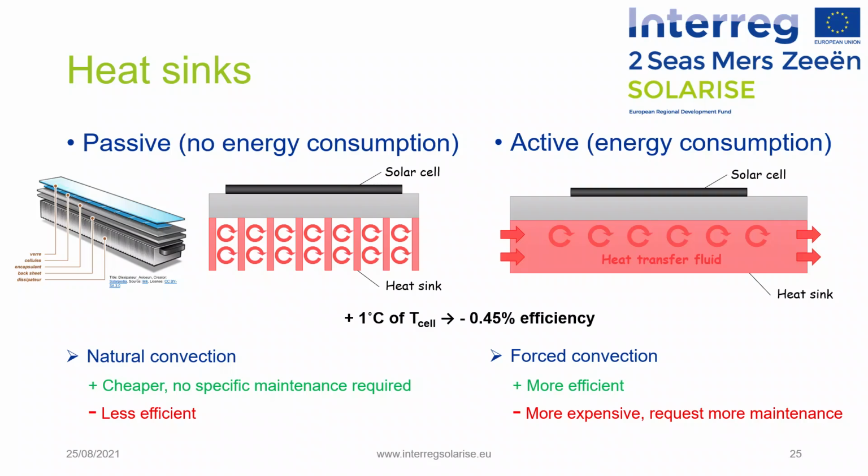Passive thermal dissipation cooling systems are mostly thermal radiators inspired by the forms that already exist in the field of microelectronics for cooling microprocessors engraved on silicon wafers. They are less efficient than active cooling systems but are generally cheaper and easier to implement in the CPV system. They also require less maintenance.